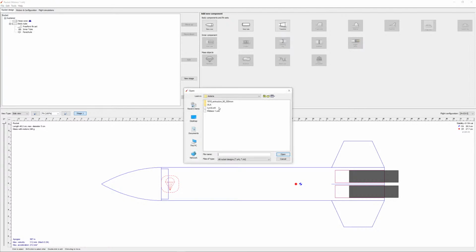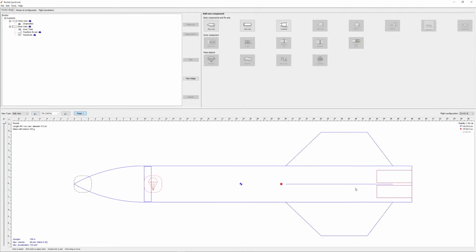However, I learned that lighter is not always necessarily better, because when it's lighter, you have to deal with something called the pendulum effect, which is where the thrust coming in down here acts kind of like if you're trying to put your finger under a pencil and balance it, it's going to get really wobbly and eventually fall over. The pendulum effect is exactly that. You're applying a force at the bottom, and if it's super light, it's going to be really hard to account for the forces coming in from all sides of the vehicle.